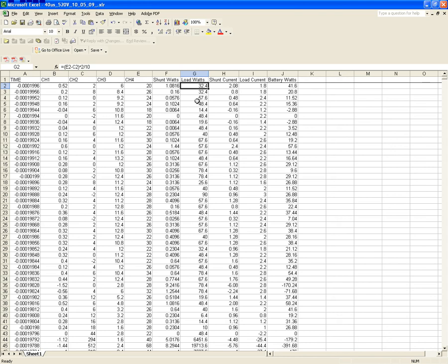Now I want to stress the point, as I mentioned in the forum, that this is a wattage that's determined by the ohmic treatment of these values. It does not take into consideration any phase shift between the voltage and the current. And we know there's going to be a phase shift there because this is an inductive resistor. There's inductance there. There's also capacitance there. And so we know that the current through that device is not truly in phase with the voltage for that device. That means the power is going to be less than what we've determined ohmically.